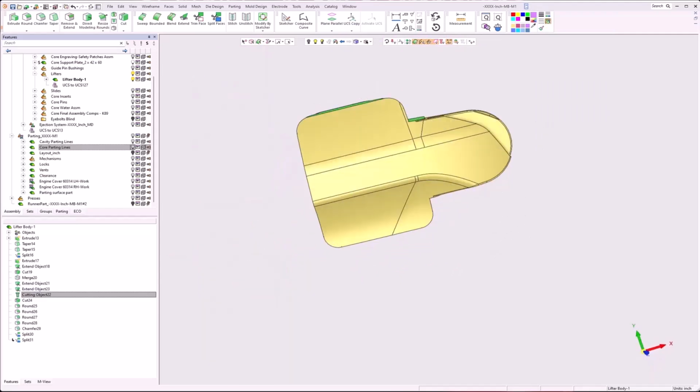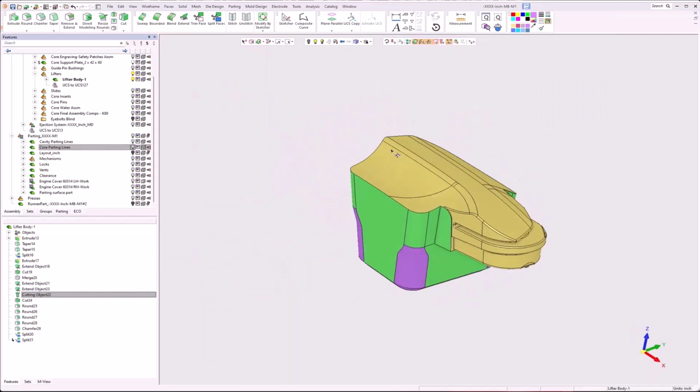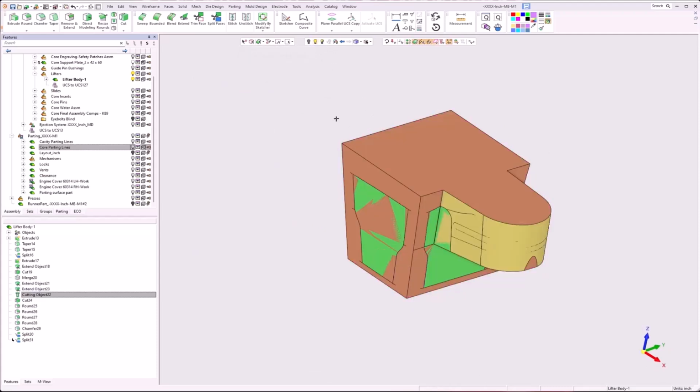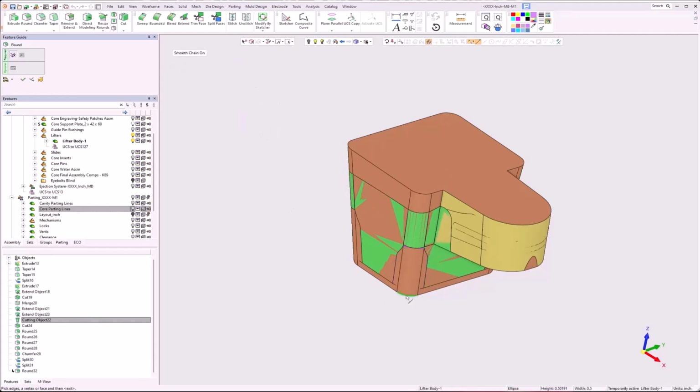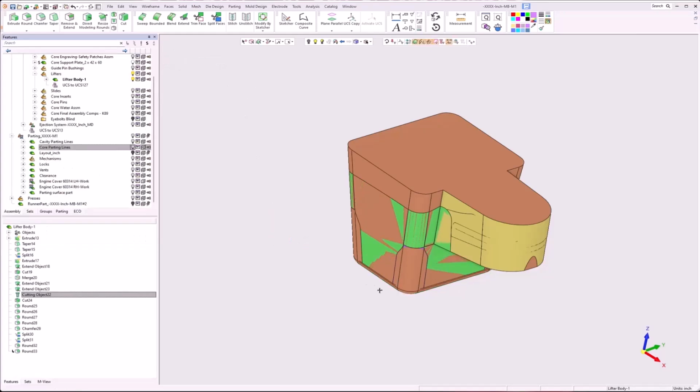So that took care of that. I'm going to display the cut object. I'm going to add the rounds to that. Now with the cut object, I can make those the 1/4 inch. I'm going to make the bottom 100th thou. Again, use your standards.